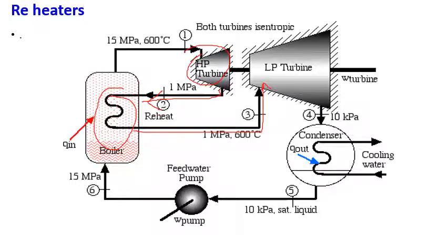We know that as the expansion work goes on in the turbine, the quality or dryness fraction of the steam drops. This is very serious because it will increase corrosion. Moreover, these turbine blades are imported and costly enough, so no user wants to take a risk on this.